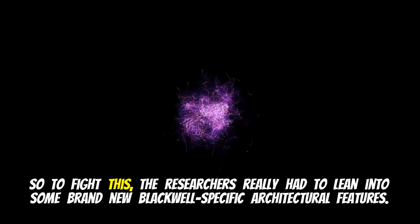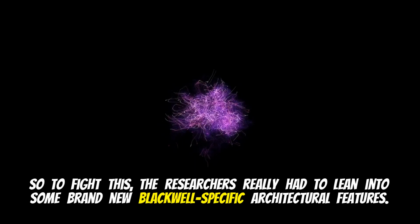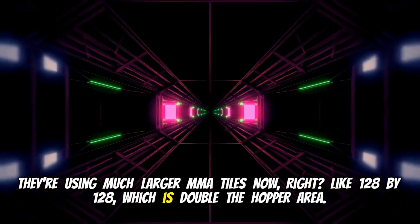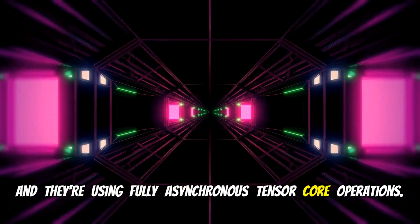So to fight this, the researchers really had to lean into some brand new Blackwell-specific architectural features. They're using much larger MMA tiles now, right? Like 128 by 128, which is double the Hopper area. Double the area. And they're using fully asynchronous tensor core operations.